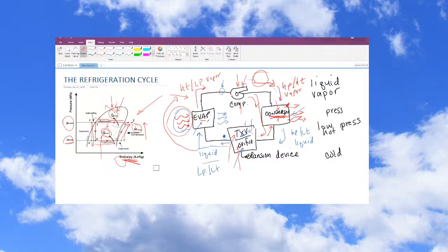So someone sends me an email and they're like, "Hey Dom, I have this problem," and I'm going through, okay, what are all the things that can cause that problem? And I don't know all those things because I've experienced all those problems, but because I understand how each system affects it. Or I think about, okay, well, this sounds like it's rich. Well, is it because there's a feedback cycle that's telling it to inappropriately go rich? Is it rich because there's a mechanical issue that's causing more fuel pressure? Is it rich because I have a short on an injector lead that's causing it to stick open? Is it rich because there's an air leak and the air leak is telling the mass airflow sensor that there's more air than there really is going into the engine? So understanding how everything works together is great.